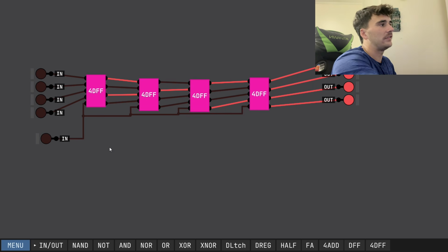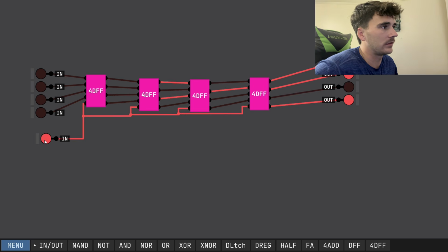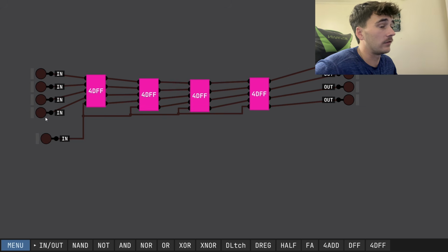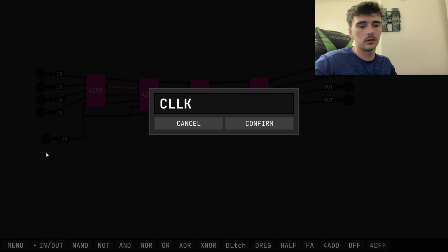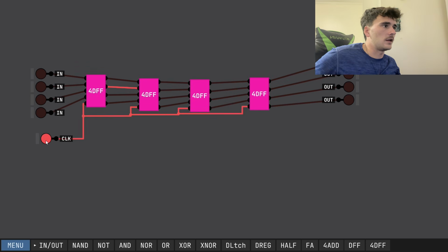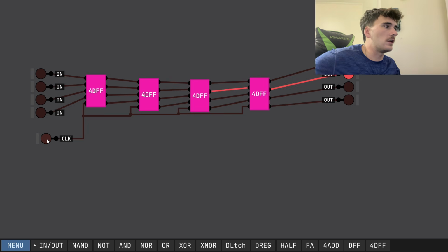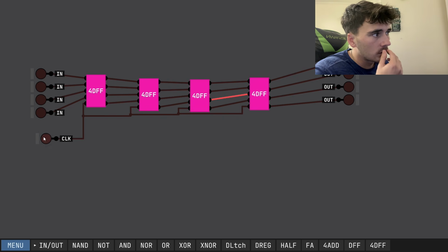Now look closely at these data flip-flops, okay? The data is going to move every clock pulse. You see that? If you didn't, I'm going to do it better. So right now we have the 4 going into the first data flip-flop. We save it. Then we clock, or we pulse the clock again. This is the clock module, okay? And look at that. The 4 is moving along. It is moving along the data flip-flop, which is crazy. Like, how is it doing this?